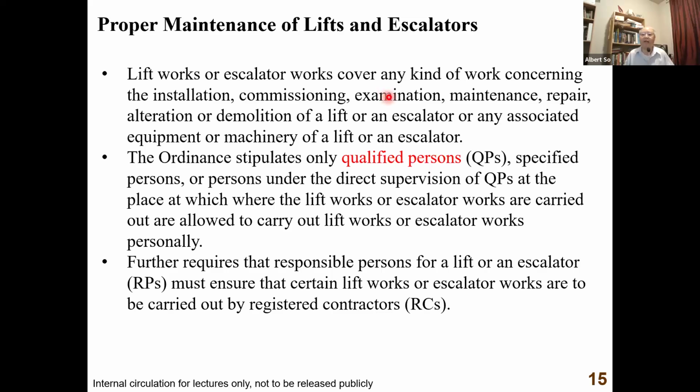Every year there is an examination, and every 5 years the examination will be more detailed. Because for yearly maintenance you don't need to involve actual load. But for the 5-year examination, you need to involve actual load. For lift, not for escalator. For escalator, you never use real load. But for lift, you use weights to imitate the passengers.